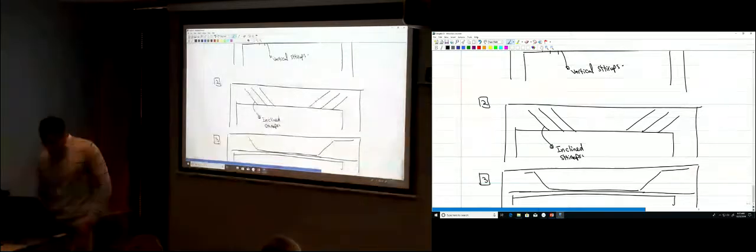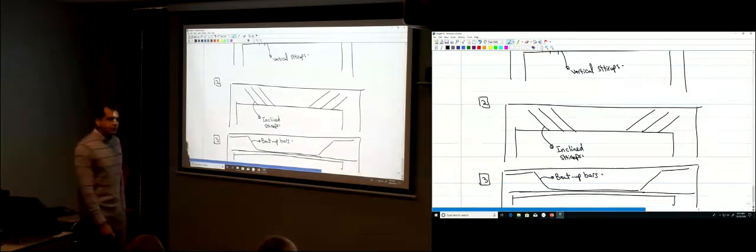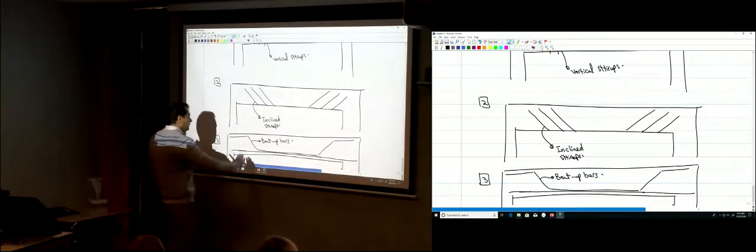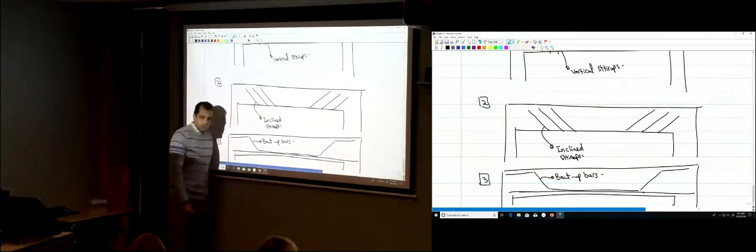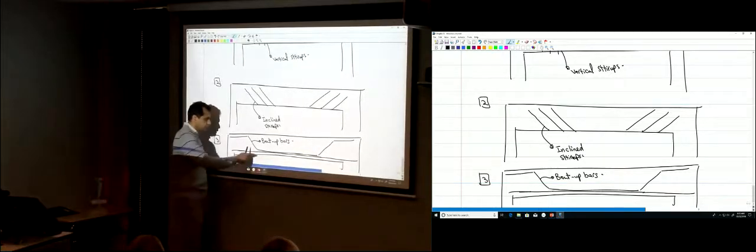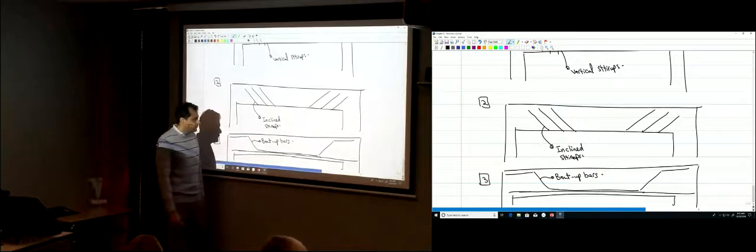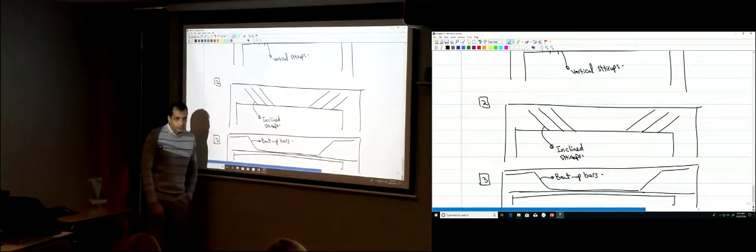This steel, as it bends up here, these bent up bars, are very useful in resisting the shear here. And it's oriented by some angle, maybe 60 or 45 degrees, whatever the bent up angle is. So it's very effective in resisting the shear, having those bent up bars.